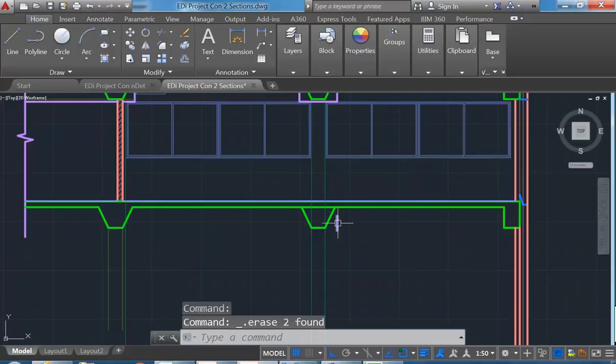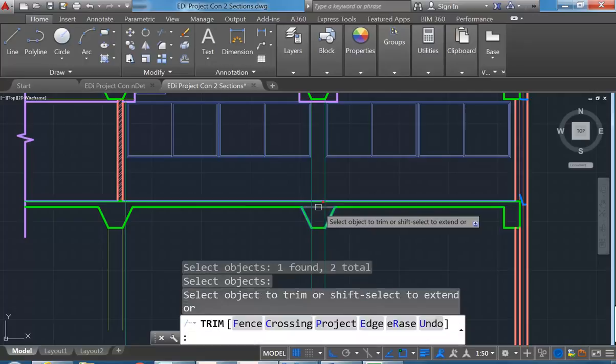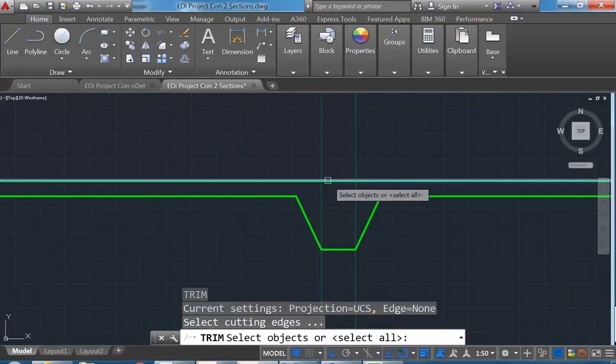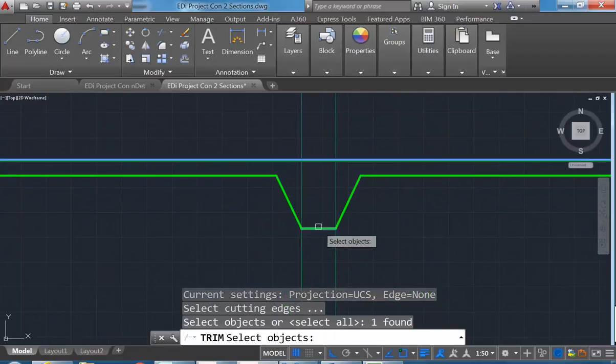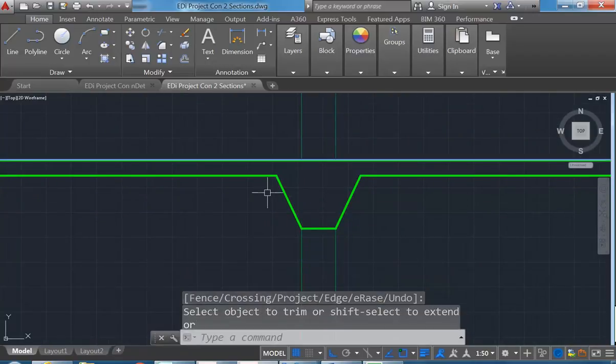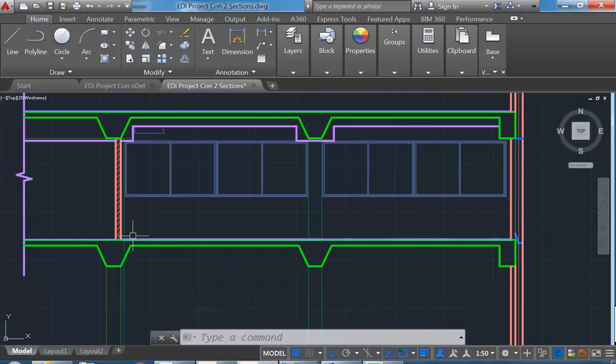Don't worry about drawing the bulkheads in on that lower story. But definitely make sure you do things like the columns, so that it's clear you know what the structural elements are and how they project through to the next level.